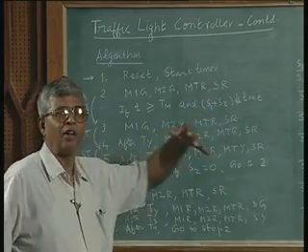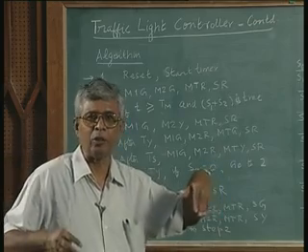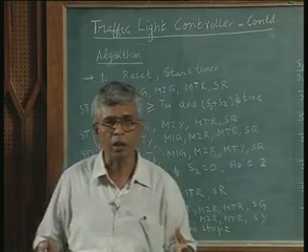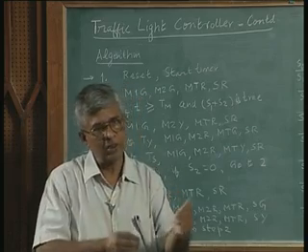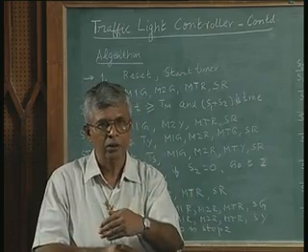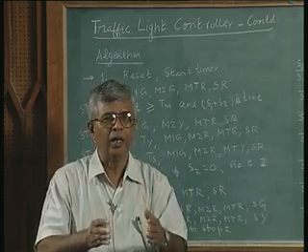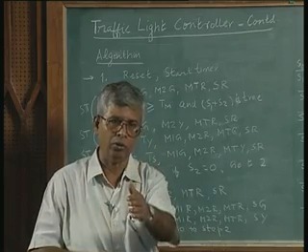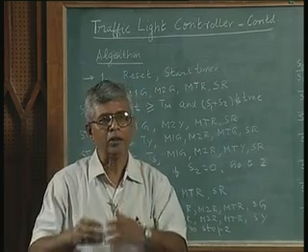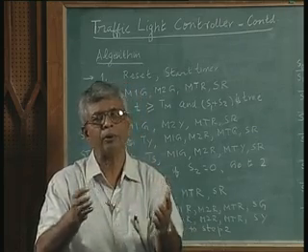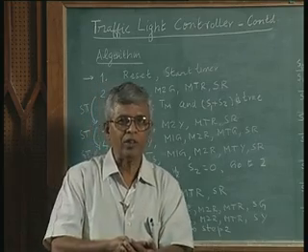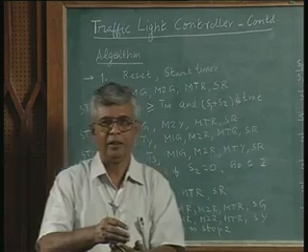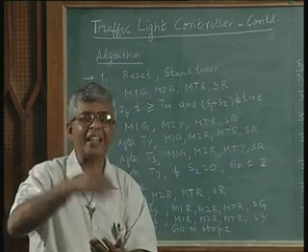In fact, I do not even have to have a sensor. I have several possibilities. Suppose I do not have a sensor at all. What is wrong? I allow the main street to be green for a while. After that time, I go from main to side, allow it for a while, and after that I go from side to main for a while, and then go back to the original. That is one simple way of doing it. The number of states will be reduced. One modification will be that one of those can be sensors, depending on which is less likely to occur.